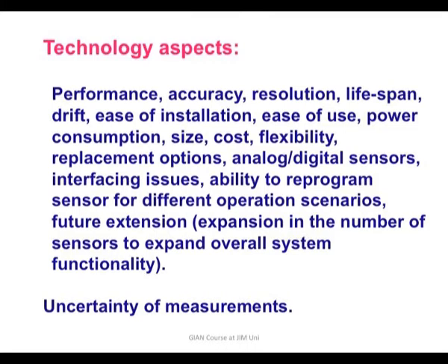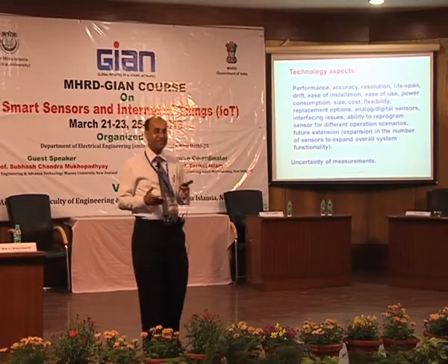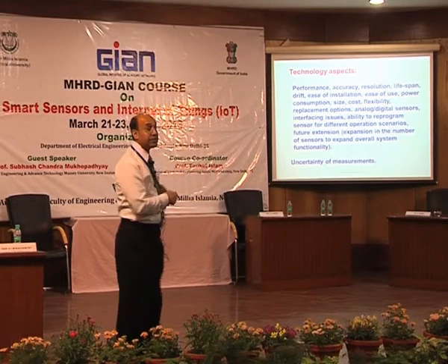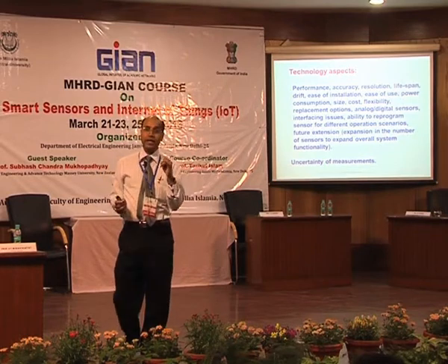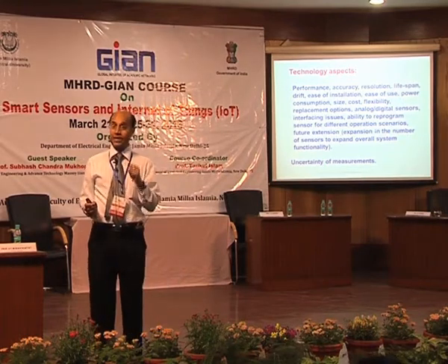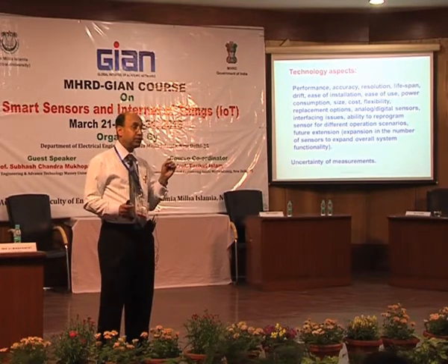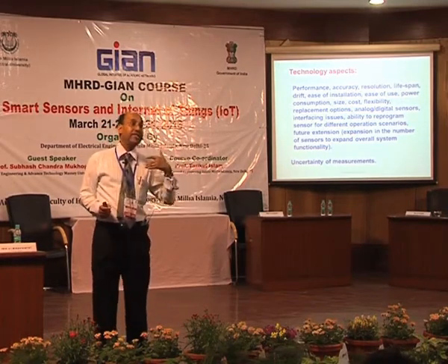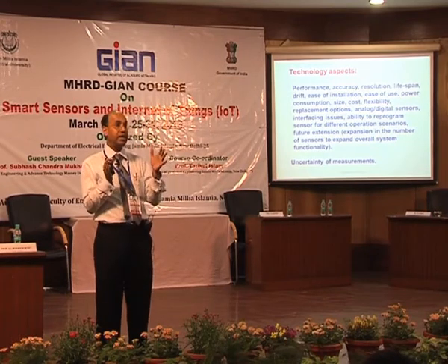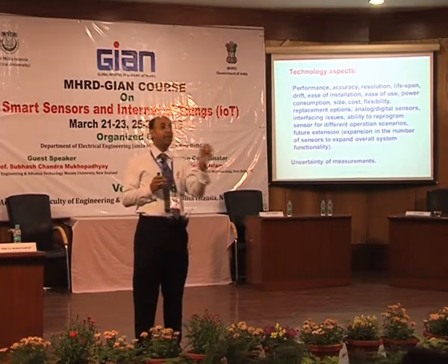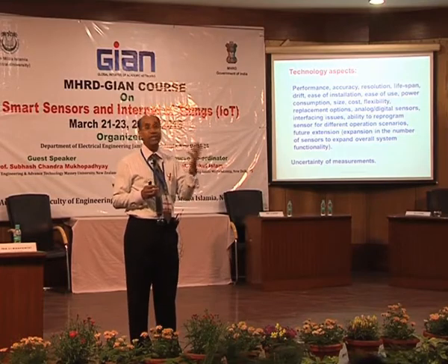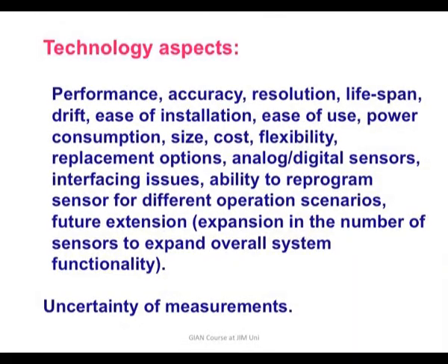So, if you have a structure for 40 years and you have a sensor for 3 to 4 years, you have to replace the sensor many times. So, it's a problem, especially for the wireless sensor network. Lifespan is actually dictated not by the sensor, but by the battery. Okay. So, when we talk about extending the lifespan, it is how do you extend the life of the battery. Battery is providing the power, energy. How can you actually use very little energy? So, it comes from that.